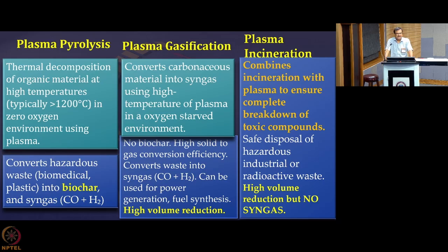So, what is that causing? This is cracking all the C, H and O bonds. Now, what are they doing? O and H are able to form O2 and H2, and they are going away, but the C which was there is not able to get removed because you are not supplying any external oxygen. So, that is pyrolysis, when you are supplying no additional oxygen.